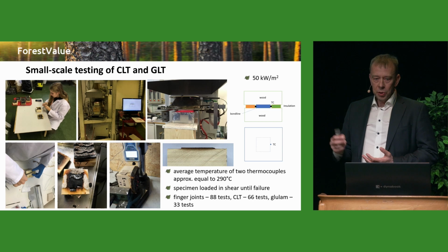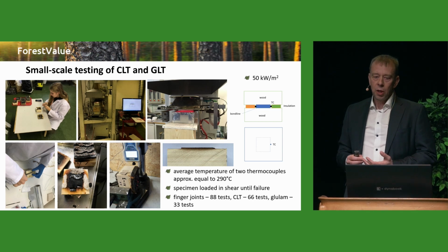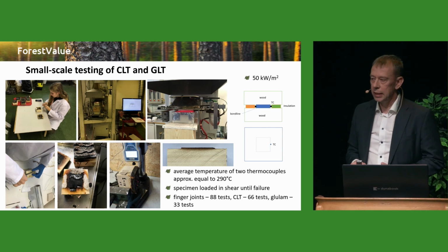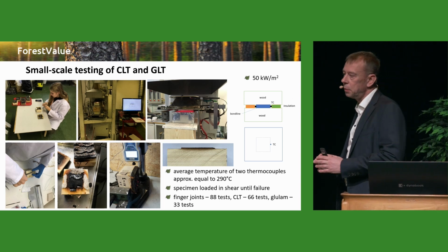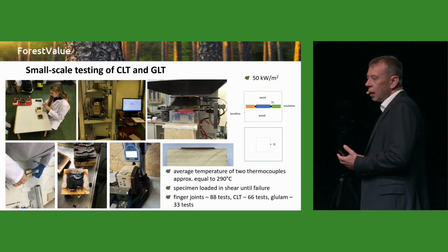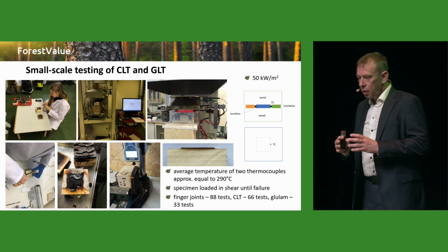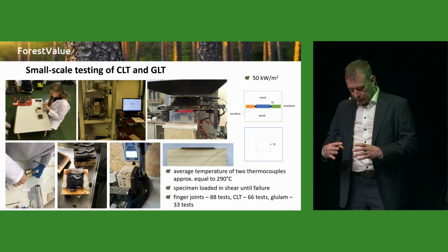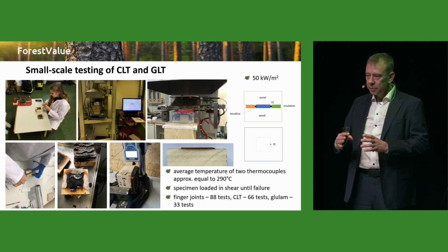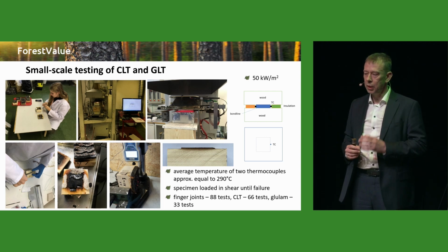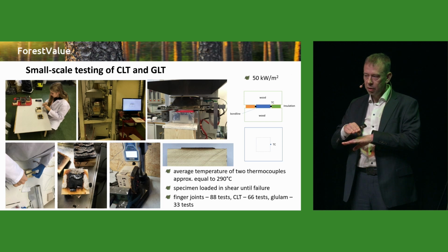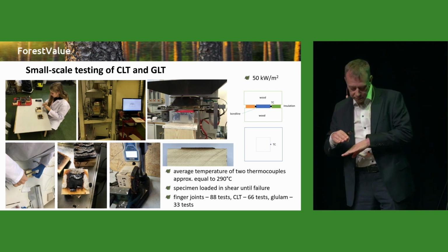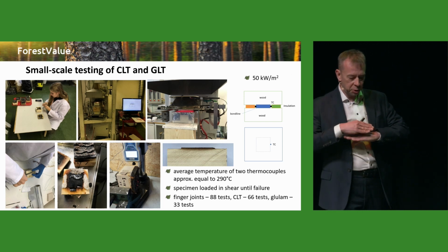One of the methods was the so-called cone heater and shear test method. So we heated our specimens. The specimen is on your right. We glued specimens 10 by 10 centimeters in plan, with 20 or 40 millimeter lamella thickness. We glued them parallel to the grain direction or crosswise.